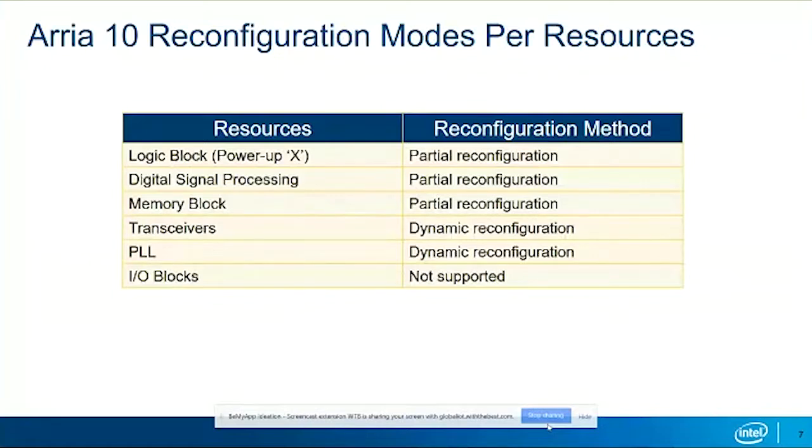And this is implemented by using a global reset after configuring the device. However, while this applies to the static region of the design, the area that's not going to change, for the area of the design that is partially reconfigurable, you cannot power up to a known condition. So you need to create the design such that you have a way of resetting these registers to a condition that will give you the functionality that you need.